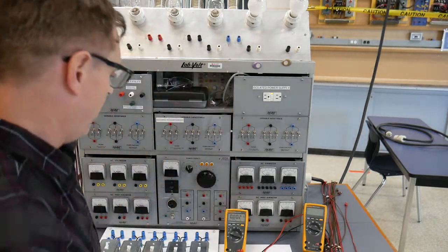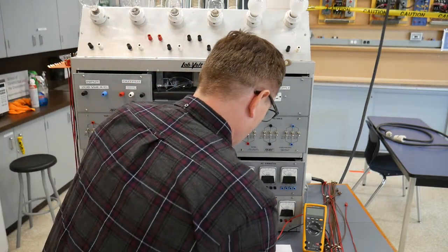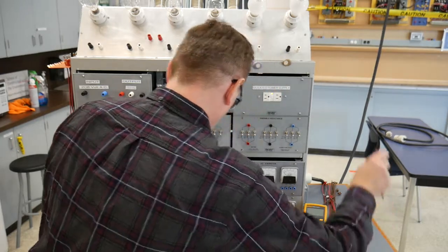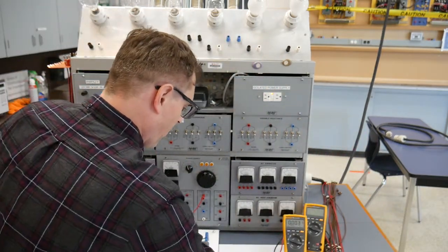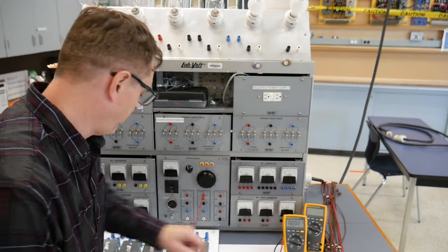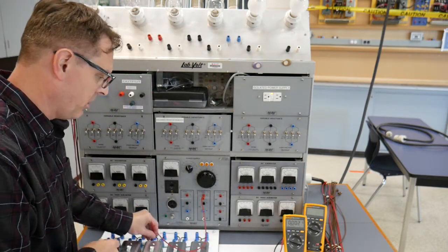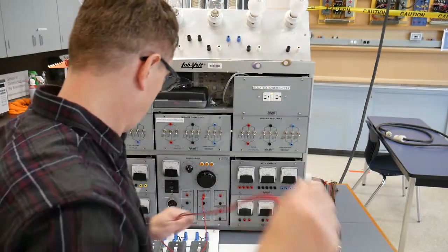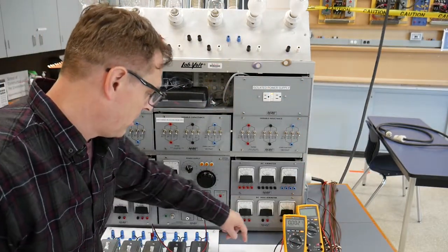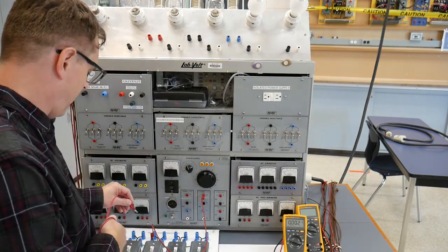So we're going to remember the drawing that we had, come out with my line conductor, find my common screw on my first 3-way, which was this bottom left corner, out with my 2 travelers, which are both up top in this case.